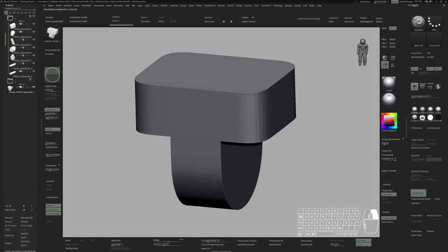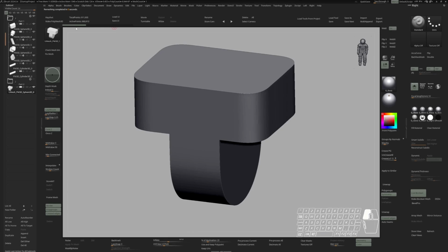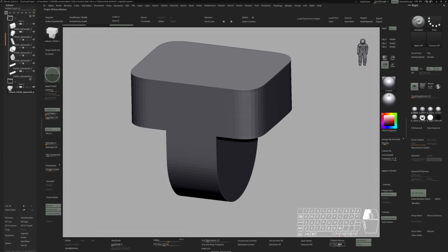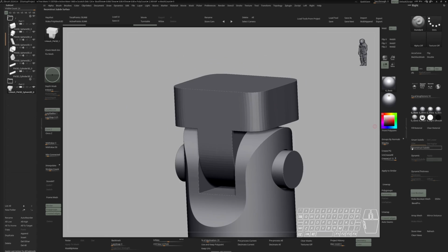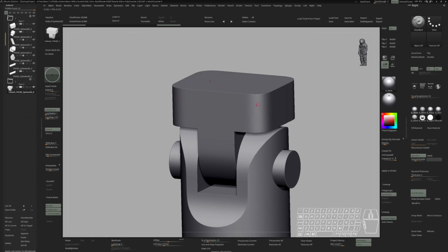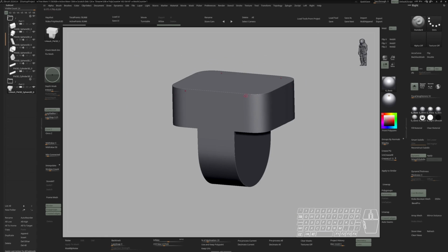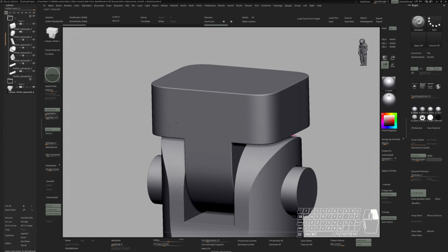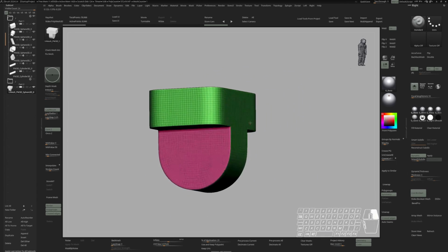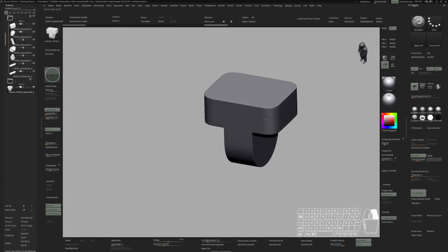Cool. So if our mesh has slight deformations, we can go back in history, click in this time of history, go all the way back, and then hit project history to get our previous shape back. And now we can turn on dynamics again. And because detect edges was turned on, we sort of have a creasing effect on our edges, so we can go down with our creasing level. And now we have an amazing clean geometry.